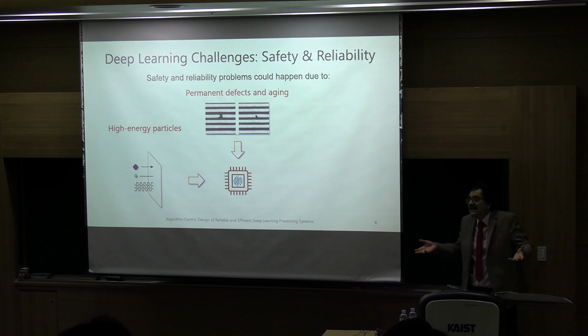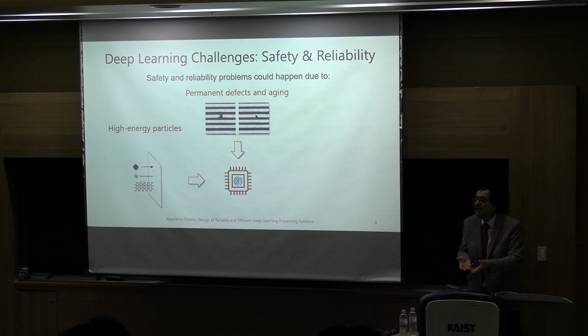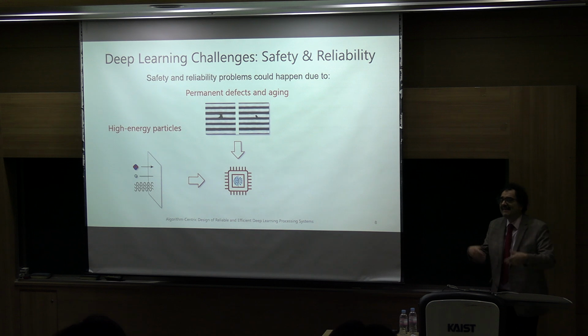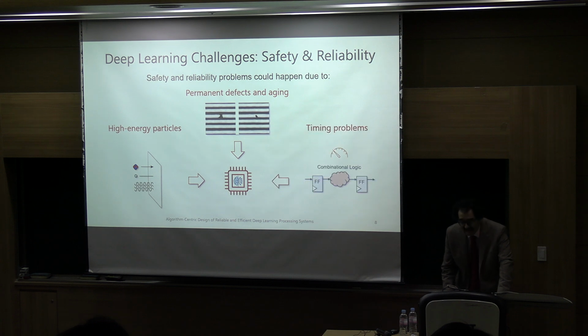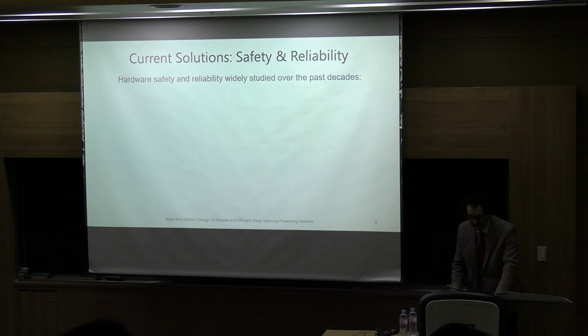And then there are other issues, that your chip may be very good. You put it in the car, and 6, 8 months later, the chip is starting to misbehave. So there are all these aging issues, there are bathtub curves that people talk about, and how to shake out these aging-related effects. And there are delays becoming more and more important and not meeting the clock cycles, and issues like this. So these are issues that have been with us throughout our journey in semiconductors.